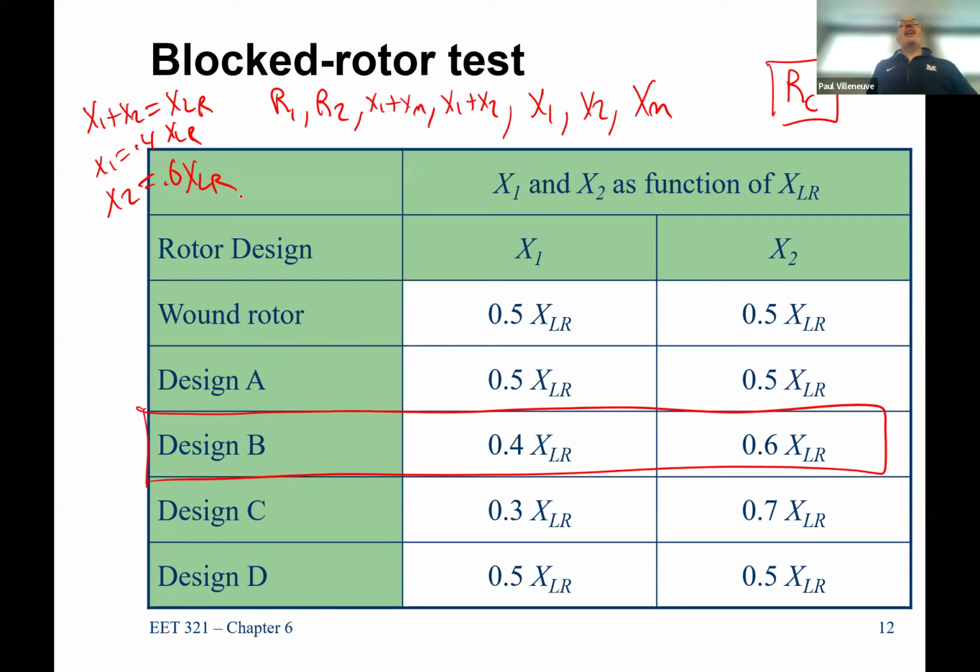So if you want to get a decent sized fan up and running, you might actually want it to be a NEMA Design D, because it might take you 5 minutes to get that fan running with a NEMA Design B. And why is that a problem? Anybody have a problem with that? Doesn't necessarily take more energy. What did we witness in lab when you were running at really low speeds? What did we see about the current? It takes a lot of current, doesn't it? And it's not putting out any real torque.